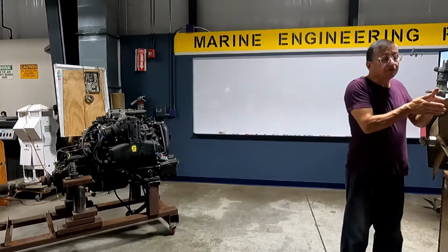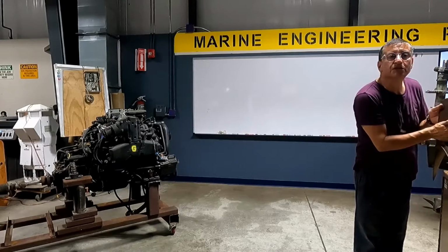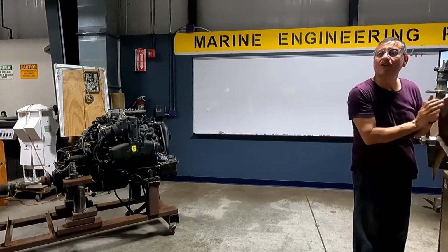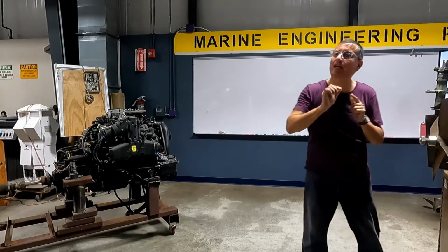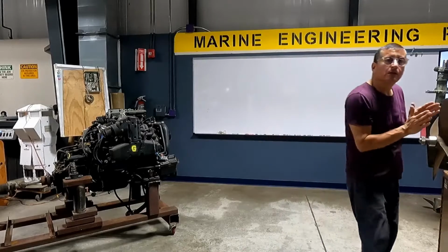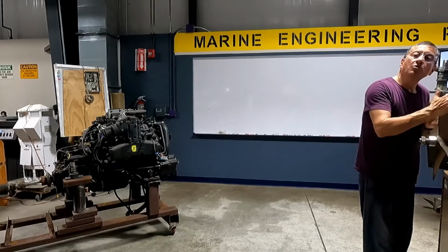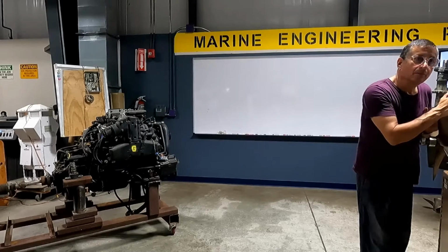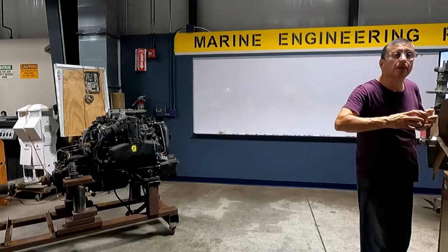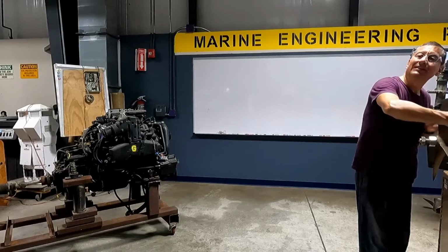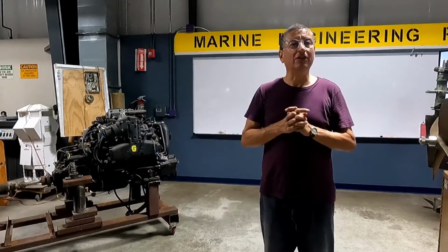It depends on the surface, the quality of the surface, and on the trailing edge, whether the trailing edge is bent or not. What happens if the trailing edge is a little bent or cracked? The flow creates pockets, and those pockets are air, they produce bubbles, and with the speed of the propeller the pressure increases, and the bubbles explode and erode the metal over there. And this is cavitation. This is cavitation.